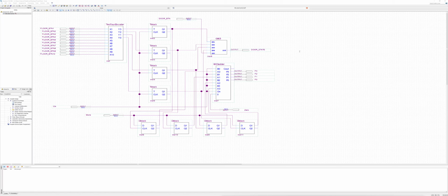And so the main unit that I used for this was an encoder right here, allowing multiple inputs but only letting one of them be active. This allows for the floors to be selected. That active signal produces n-bit output signals containing the binary information. Using a BCD adder, we're allowed to combine additional clock cycles and previous input data to gain a 4-bit output.